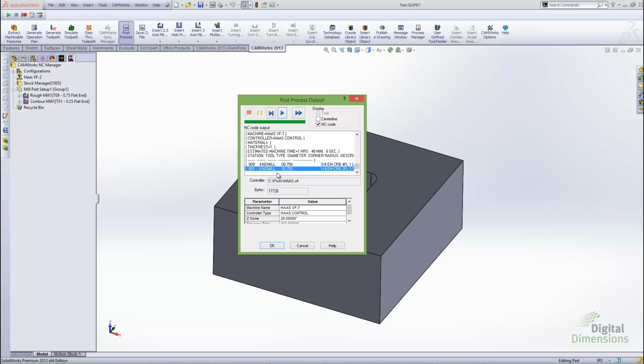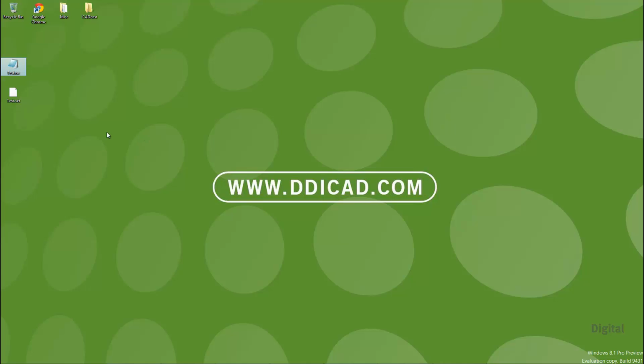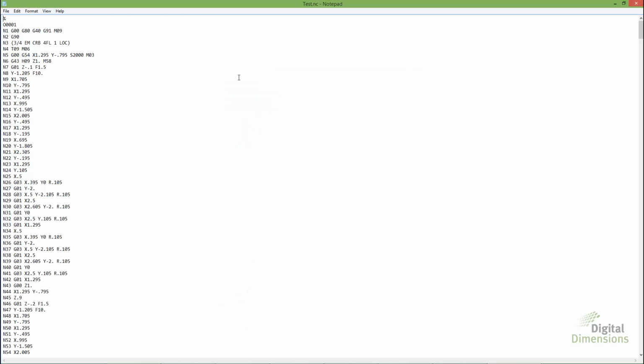So basically I want to take this tool list that's now showing up in the .set file and put it at the top of my code. Opening up that code real quickly, here's my test.nc file, and at the top I want to add a tool list showing every tool, the tool number, and a description, diameter, and so on. So that's the goal.